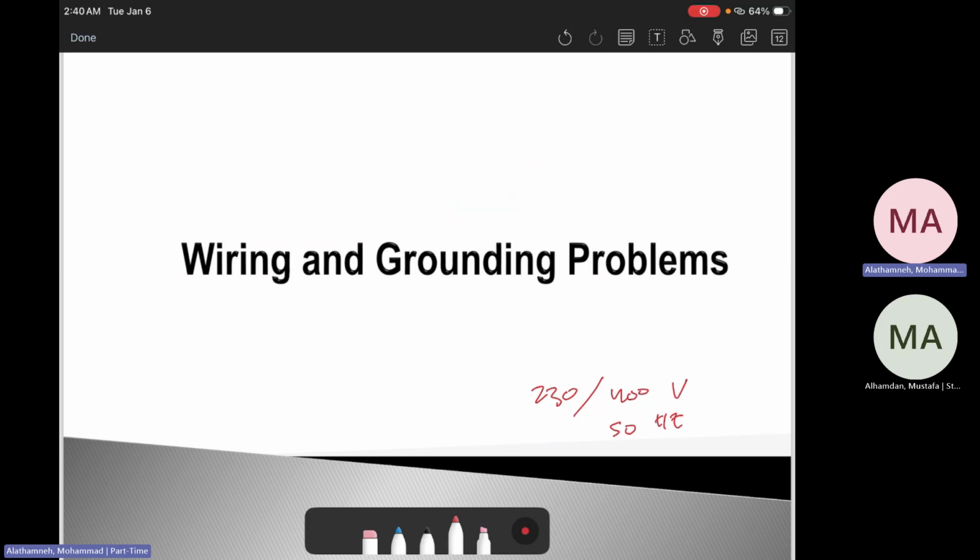So it is important to study grounding, because there are a lot of grounding and neutral problems, and they can be worse with modern loads, especially LED drivers, phone chargers, variable frequency drives, UPS systems like uninterruptible power supplies, and IT equipment like computers, PLCs, etc. These devices are everywhere right now, but they don't behave like ohmic resistors. Ohm's law does not apply to them because they are nonlinear loads.